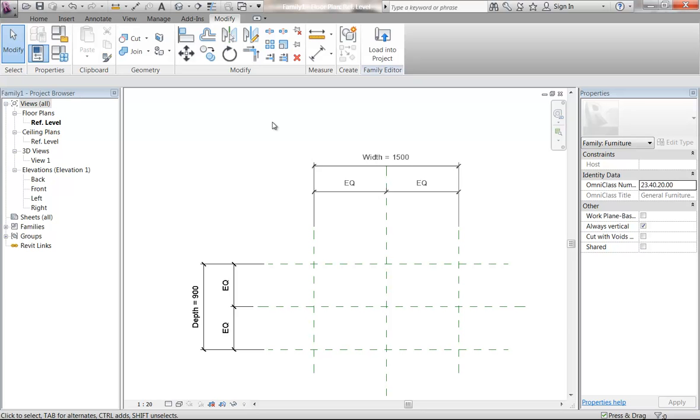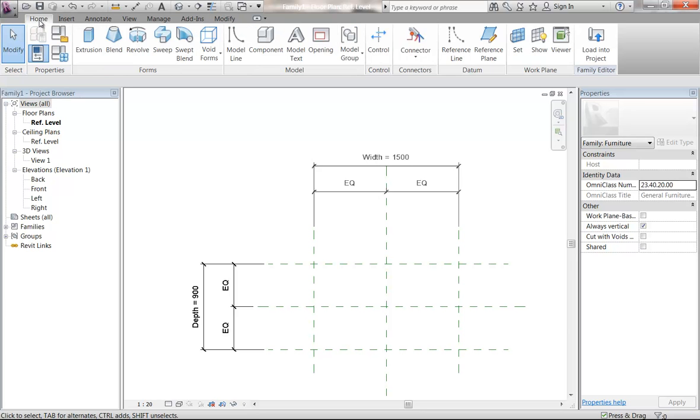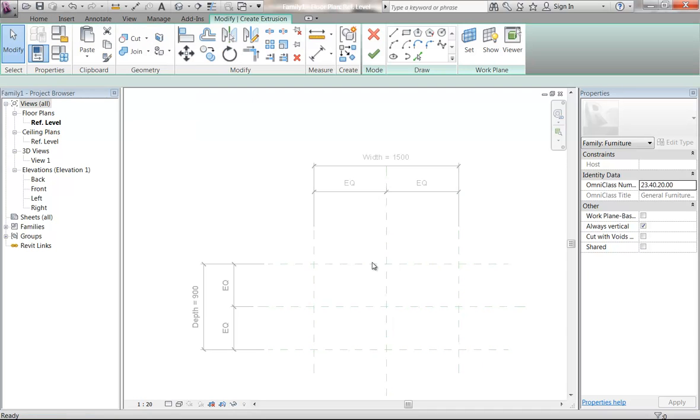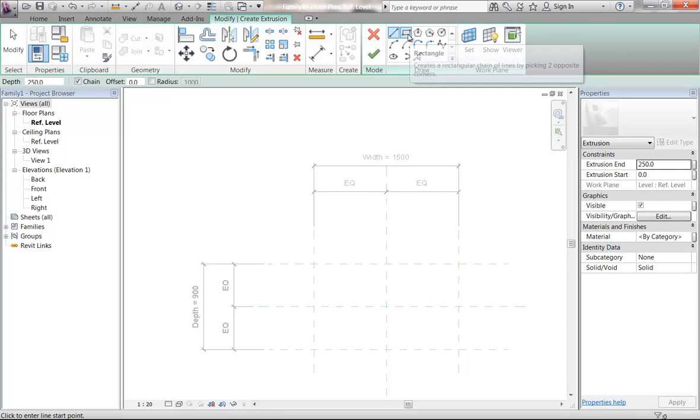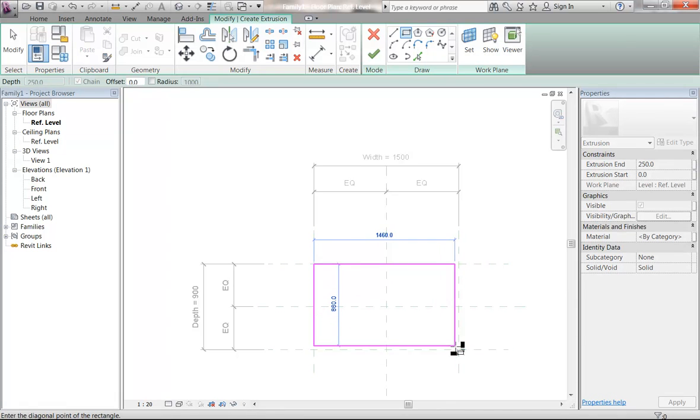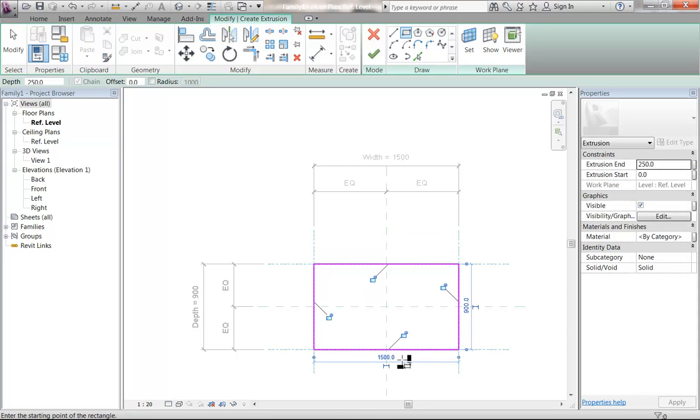So anyhow, though, this will work now with my Revit solid. So I'm going to draw an extrusion using the rectangle tool, and I'm just going to snap to the intersections of these reference planes to draw my 2 points for my rectangle, and then, this is the most important bit, lock all 4 of them. If you click to one side after you do that, you'll lose the lock symbol, so make sure you do it right away. And so there we are.